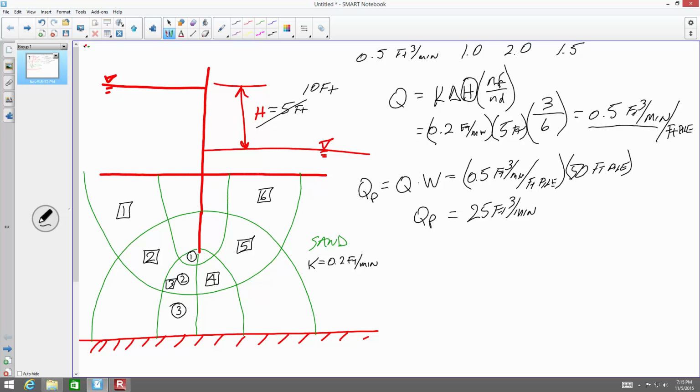If the sheet pile is extended downward to cut through more of the sand, what happens to the flow? It increases, it decreases, it stays the same. The solution cannot be determined. Boy, you hate them, don't you? The sheet pile is extended deeper. So I decided to drive the sheet pile down a little deeper in the ground. Does the flow decrease, increase, stay the same? Solution's undetermined. Increase or decrease the number of flow channels if you do that?